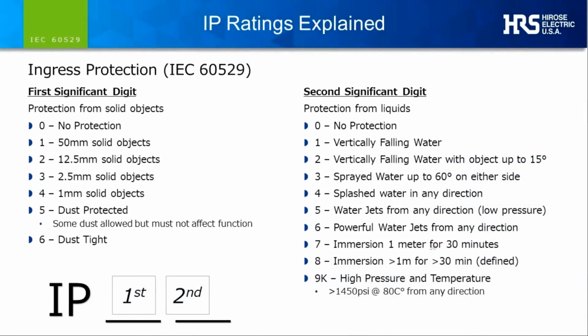Here we can see an example of the different IP ratings, all in a big chart here. When folks say that they're looking for an outdoor connector, they are typically referring down the bottom here to an IP67 or IP68 requirement. But don't discount the other options. Just because a connector or device is rated to IP67 does not mean it passes IP66 water jet testing.